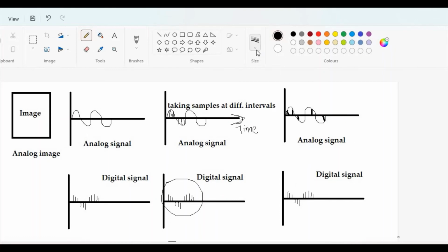Now when these samples were taken, if we trace them, the original signal can be created, right? But in this case, if you trace these, do you think the original signal will be created? It's going to go something like this. So if wrong samples are taken sometimes, the actual frequency in the continuous signal will be distorted in the digital signal.